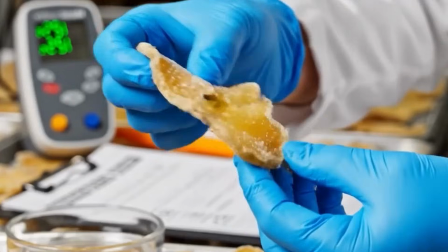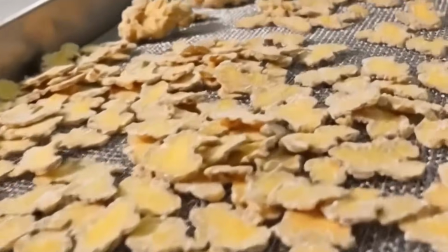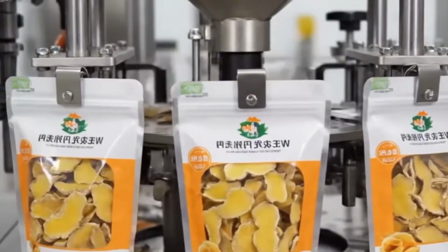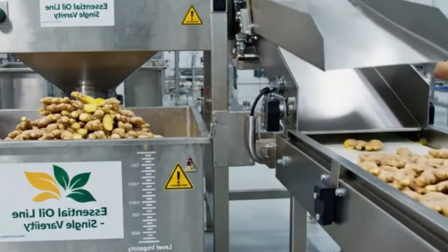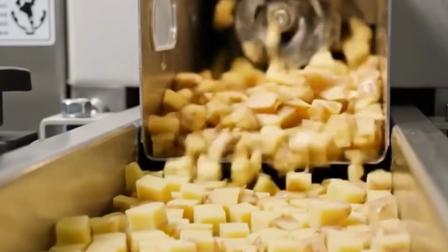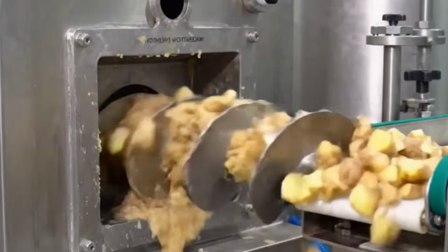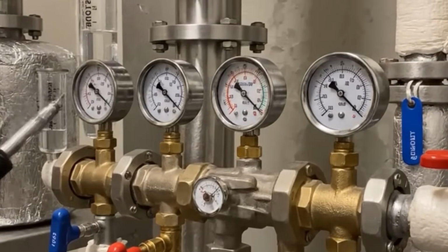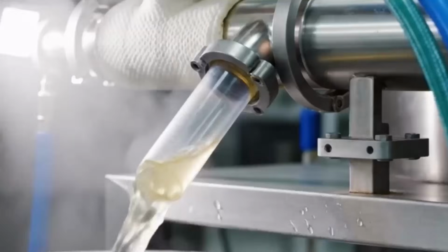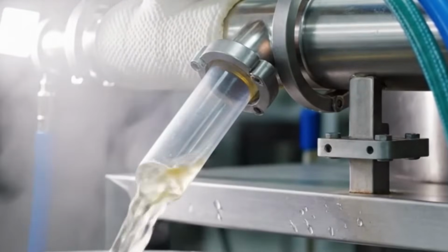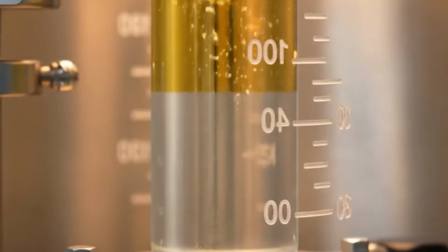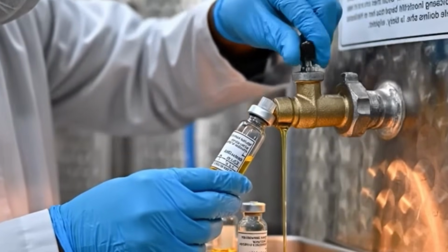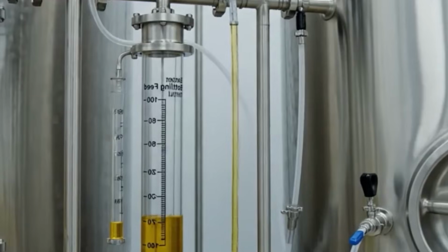The finished containers are then grouped into multi-packs. Bottles are sorted and arranged into clusters using pneumatic sweep arms and placed into molded plastic carriers or corrugated trays. Cans are conveyed into shrink wrapping units, where sets of 6, 12, or 24 are collated onto a moving belt. Polyethylene shrink film is dispensed over the groups and sealed at the edges. The packages move through a heated tunnel with recirculated hot air that shrinks the film tightly around the cans, securing them in a stable bundle.